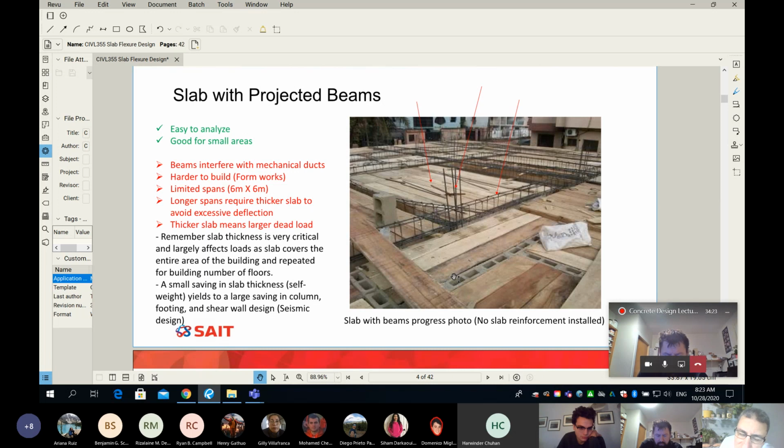I know that in this course we don't talk much about seismic, but seismic is the earthquakes. The earthquake is a lateral load and it's a function of the self-weight. If you have lots of self-weight, you have lots of earthquake problems and forces. Do you guys know that if you have lots of self-weight, you have a problem with the lateral loads from earthquake?